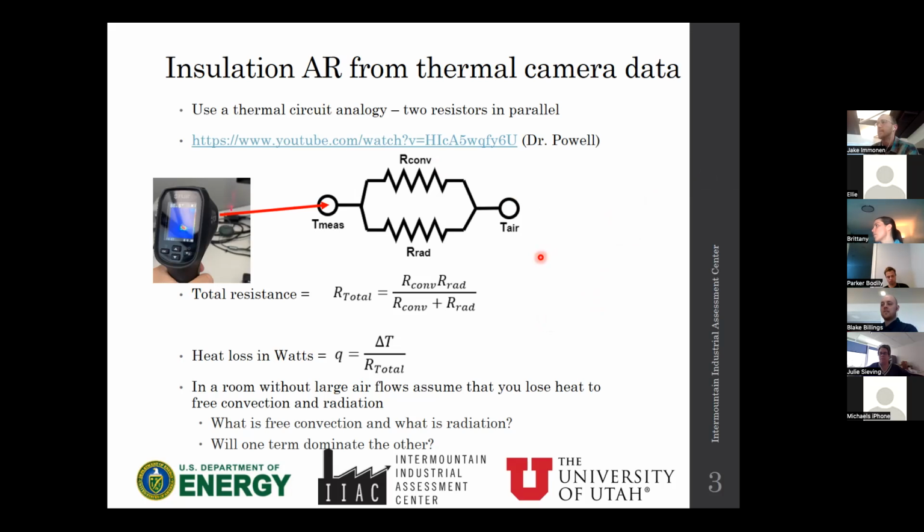Yeah, exactly. That was what I wanted to point out. For very hot things, radiation is temperature to the fourth, so it's going to be a lot higher at higher temperatures. Radiation is going to be dominating for higher temperatures. That's just something to keep in mind.